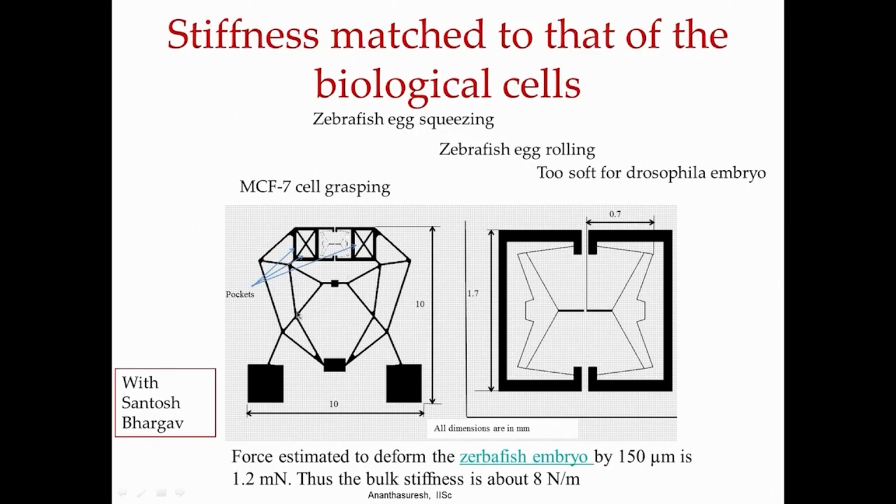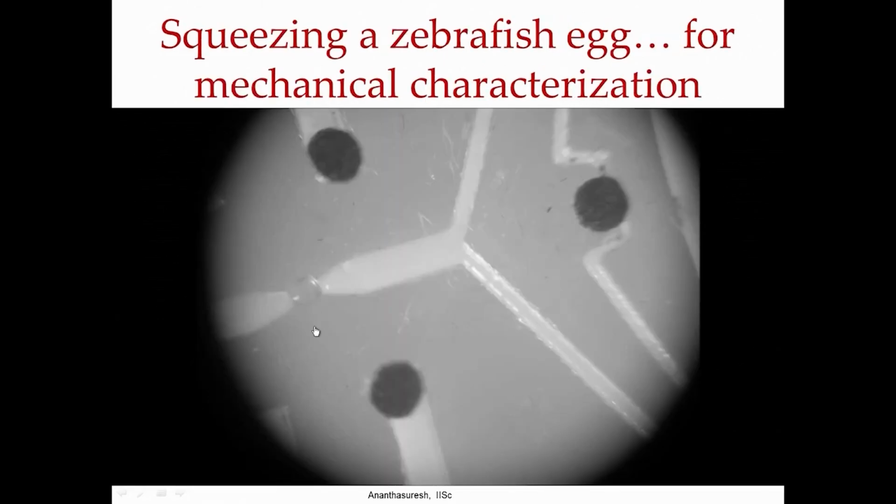If you want to pick that up, you take a bigger compliant mechanism, put in that a little small compliant mechanism, whose magnified view is shown here, and here is where the cell would be grasped. And some of the beams here will be very small, they can be as small as 5 microns in width and a couple of microns along the thickness direction, with which you can hold zebrafish embryo, single cells, biological cells and so forth. Here we have a zebrafish embryo.